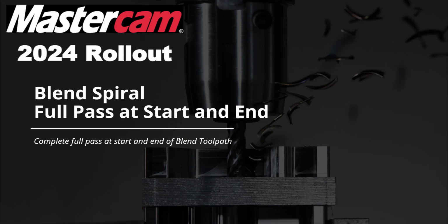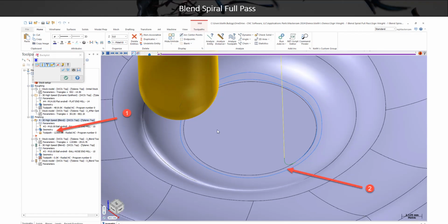They also, on the blend spiral, or on the blend toolpath, it has a spiral option. Some of our other toolpaths have that as well. Instead of doing a cut and then doing a step over, it slowly kind of morphs to the next path. And the way that the blend path usually works is the first cut is exactly centered on your blend curve, and then the last path is on your last blend curve. But when you went to spiral, it didn't do that. It would start on your blend curve, but immediately start its spiraling pattern, leaving it, which by the end of your first pass could leave a little bit worse finish there, or some larger cusps than elsewhere.